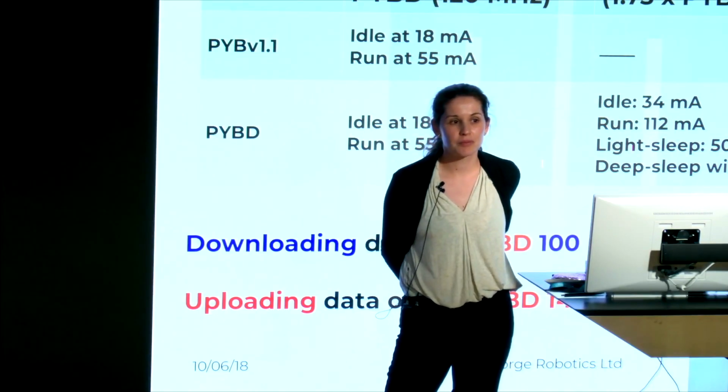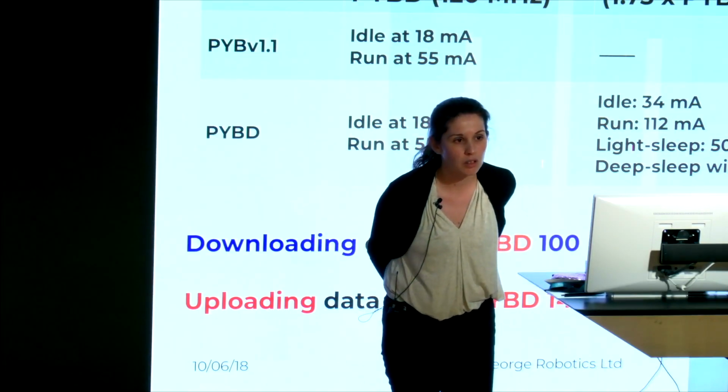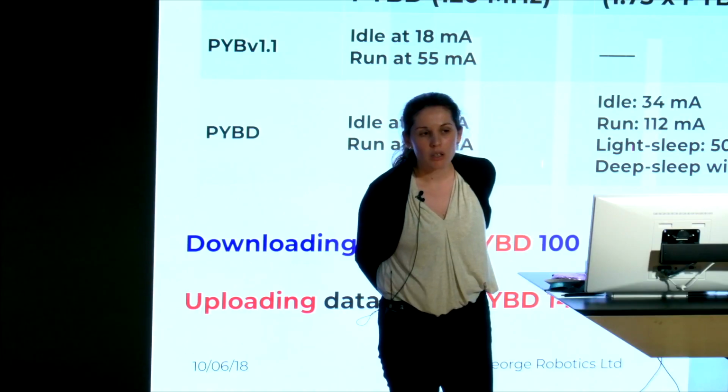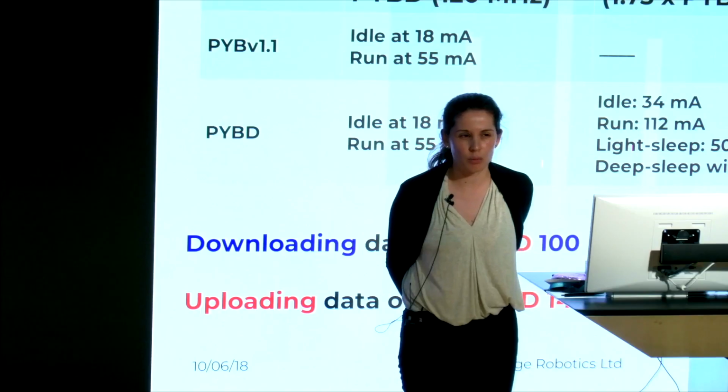Can you tell me whether MicroPython is sort of true real time, or does it run on a real-time operating system? Which operating system do you recommend using it with? And can it be deterministic real time in terms of the interrupts if you're trying to build a controller? Deterministic real time in the sense that it could respond quickly, within a guaranteed time period, in the way that microcontrollers traditionally do? Yes. I didn't quite get the question with the operating system.